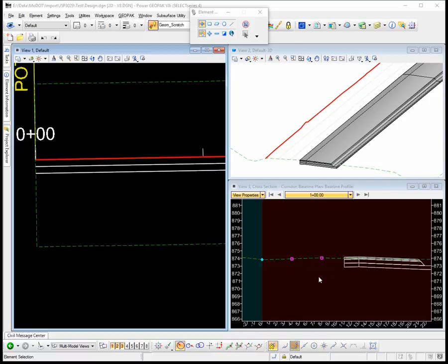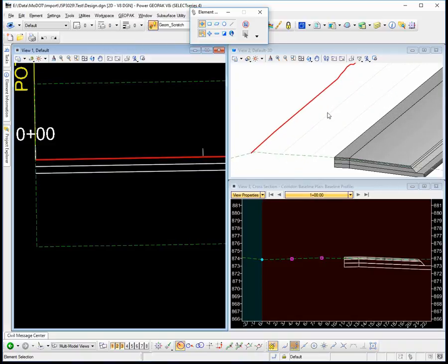So there's a couple of ways that we can do this, one more efficient than the other. In this first example, I'm actually setting point controls on these two lines, and so I have an alignment called EX1 and I have an alignment called EX2. On each of these alignments, I have assigned the existing ground as the profile to dictate that vertical information, and so you'll see these gray lines here that represent the 4 and the 8 foot where the profile is set by the ground.